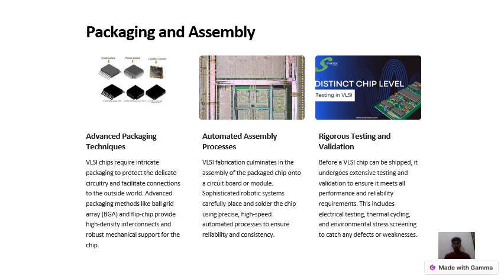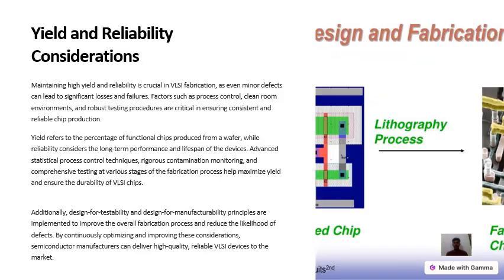Rigorous testing and validation. Before a VLSI chip can be shipped, it undergoes extensive testing and validation to ensure it meets all performance and reliability requirements. This includes electrical testing, thermal cycling, and environmental stress screening to catch any defects or weaknesses. Yield and reliability considerations. Maintaining high yield and reliability is crucial in VLSI fabrication, as even minor defects can lead to significant losses and failures.